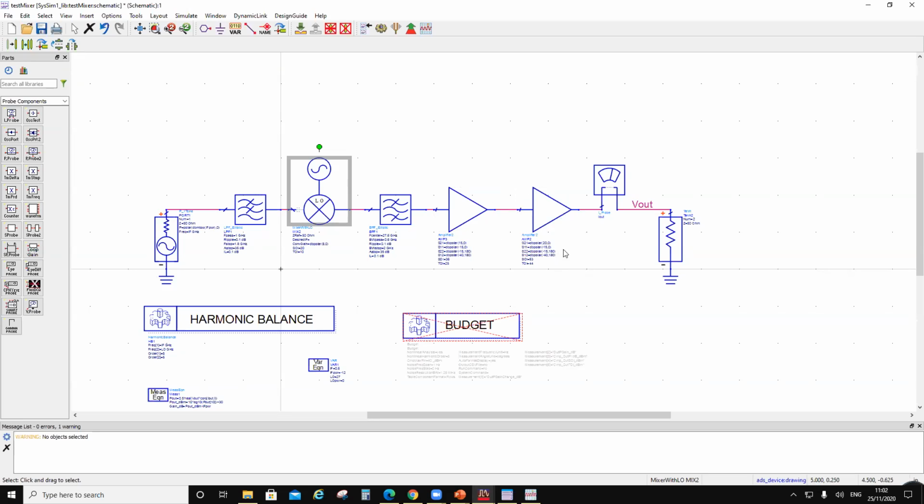So here it is 43. So the gain budgeting is considering what is to be delivered and what the DAC output is going to be. So the remaining stuff is going to be the transmitter gain. So accordingly, you are going to put gain stages, right? And this TOI has to do with the output delivered power.